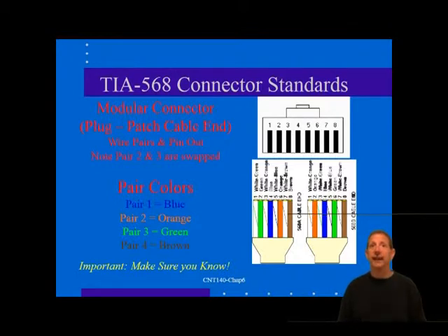The official stance of the TIA is that the A pattern is preferred. The statement certainly applies to new installations, since it will be problematic to switch the pattern in an older installation. You could also justifiably choose the B pattern if Avaya or Lucent or AT&T components are used, since that is their standard offering. Now, there's a great debate over which pattern is used the most. The truth is in the hearing. The customary pattern varies widely, depending upon whom you ask and what part of the country or the world you live in. Personally, I've always gone with the 568B.